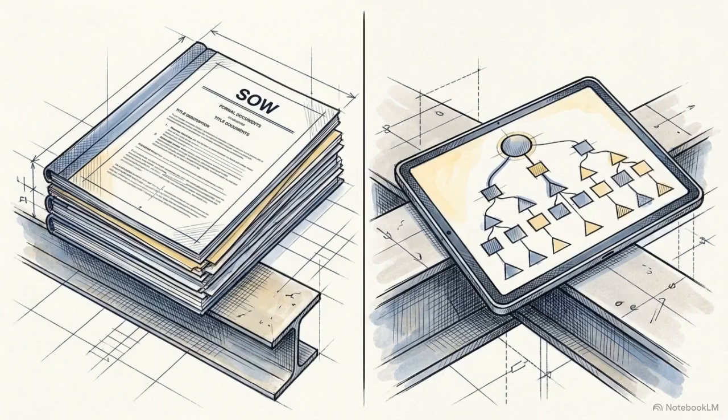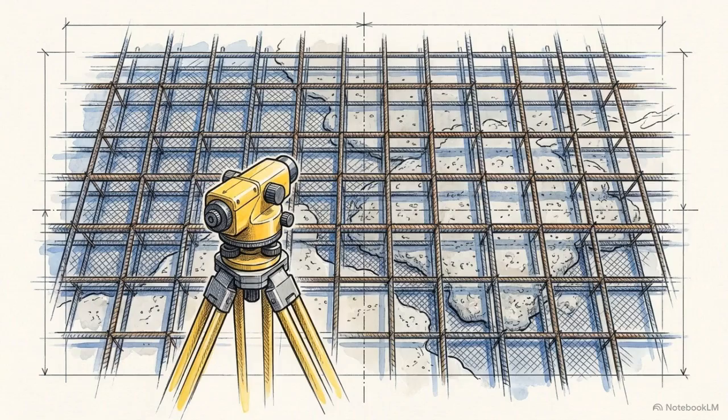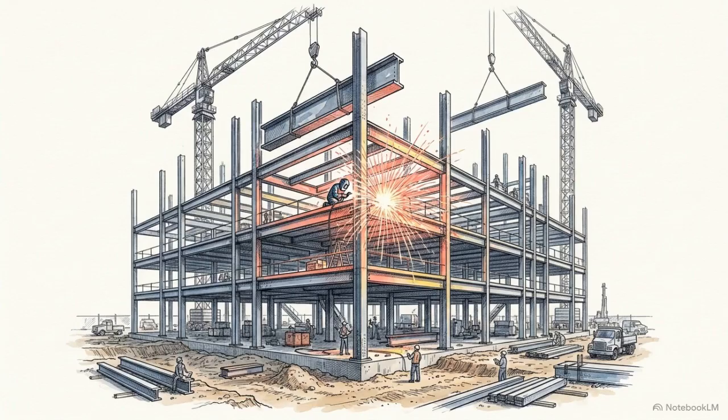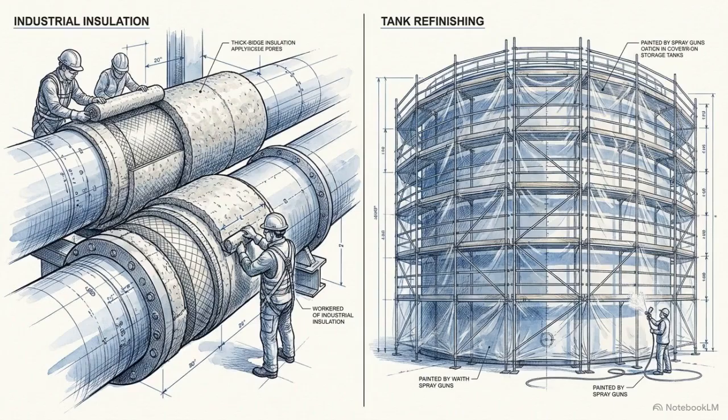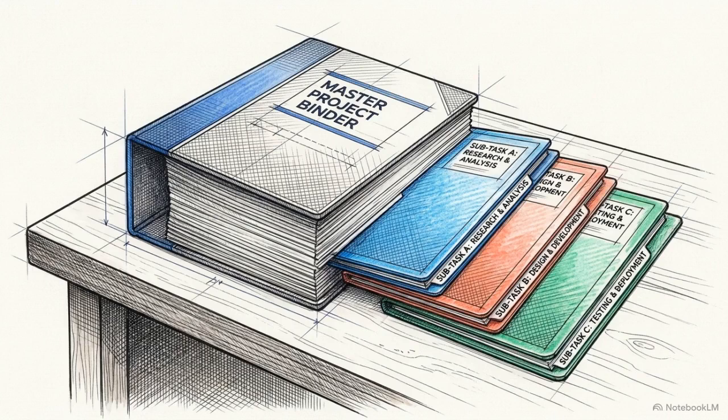The SOW and WBS provide the necessary engineering structure for quality control. They ensure that every inspection activity is rooted in the project's defined hierarchy, preventing critical tasks from being overlooked in the transition from planning to execution. Complex work elements, like massive insulation or painting operations, can overwhelm a single inspection plan. To maintain clarity, these lengthy WBS elements require separate, dedicated ITPs.